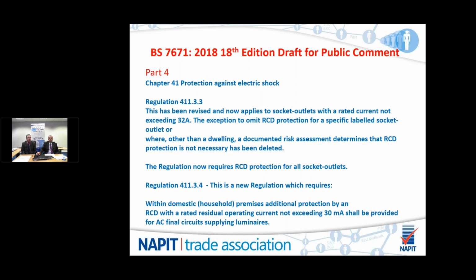Also, we have a new regulation, 411.3.4, and this requires within domestic and household premises that additional protection by an RCD not exceeding 30 milliamps shall be provided for all AC final circuits which supply luminaires. So this is an increased use of RCD protection for both socket outlets and for luminaire circuits within domestic premises.